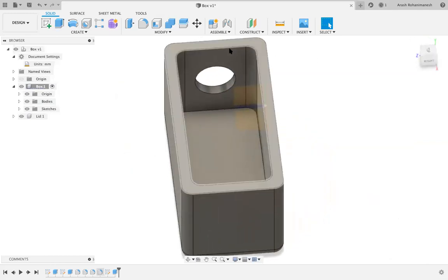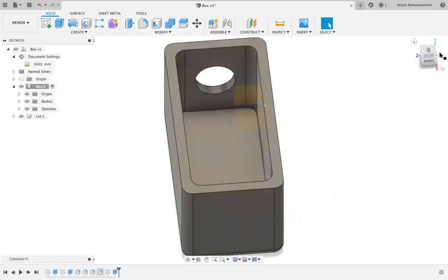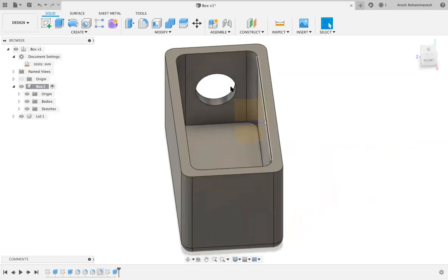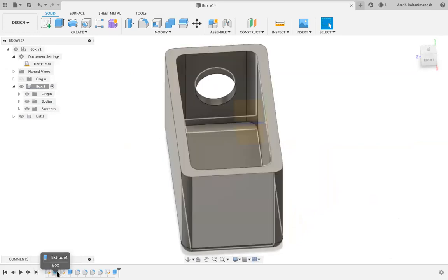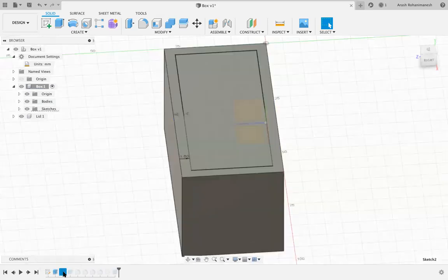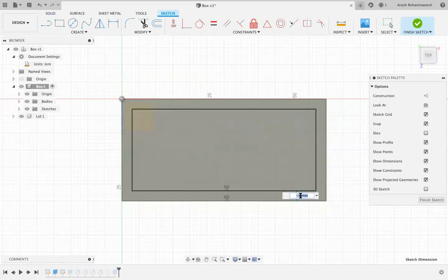So no matter how thick I make this wall here, this hole will always be there, right? Because sometimes, let's say you specified, I want this to be 3 millimeters. Well, let's say you go back and make, let's just do that just for the fun of it. I want to be able to demonstrate this as well as I can. So where did we do the offsets? I believe it was right here. So you see how this is 3? I want it to be -4.